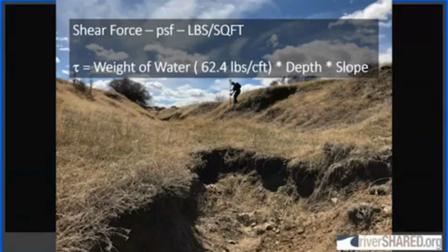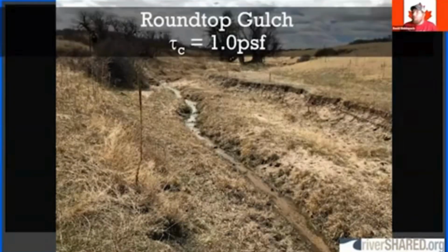So one of the things that we do in looking at floodplain design, we look at a channel restoration design, which could be based on the 100-year channel, the 50-year channel, the bankfull channel. We say design for a range of discharges, but then we also look at the floodplain characteristics and how do we design a floodplain for the vegetation that's available to recolonize or for the vegetation that we replanted.